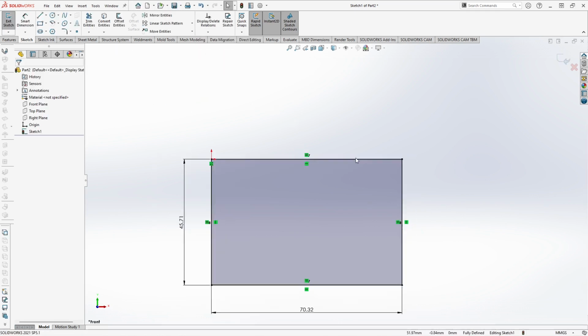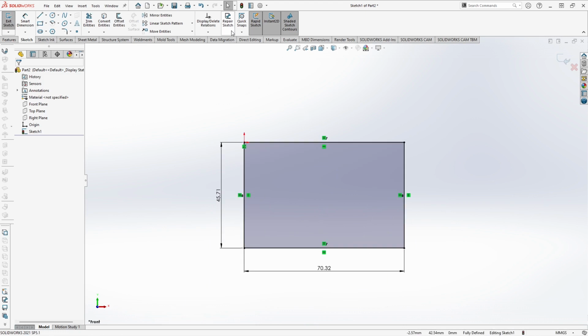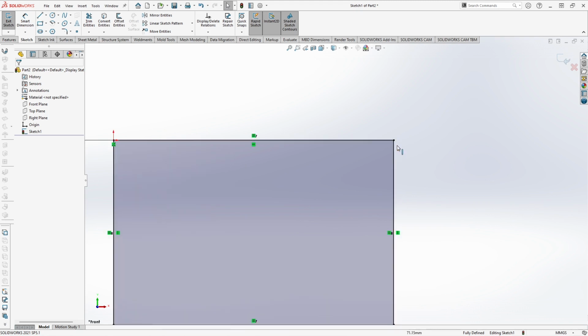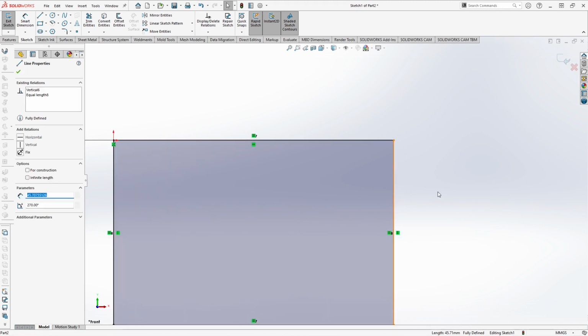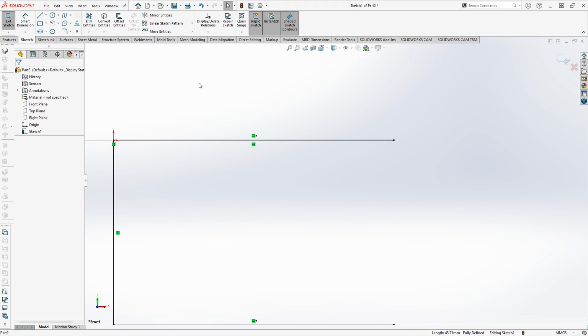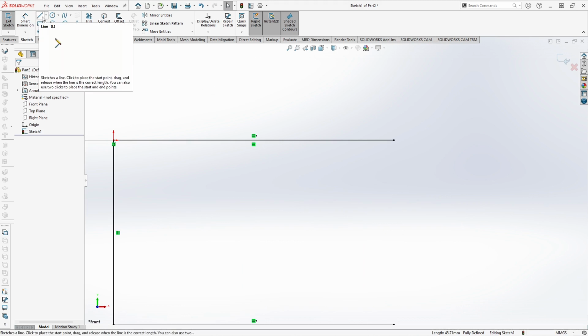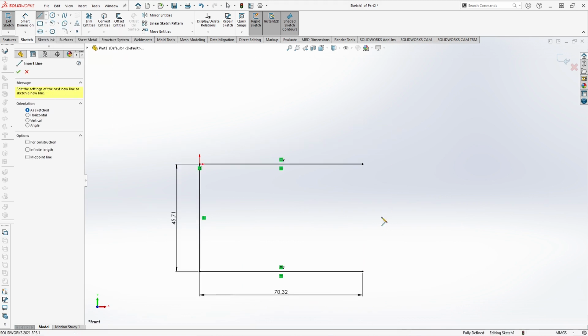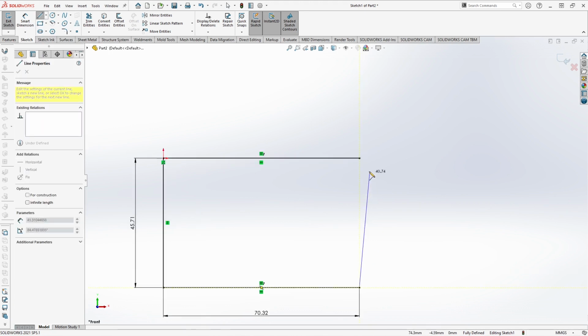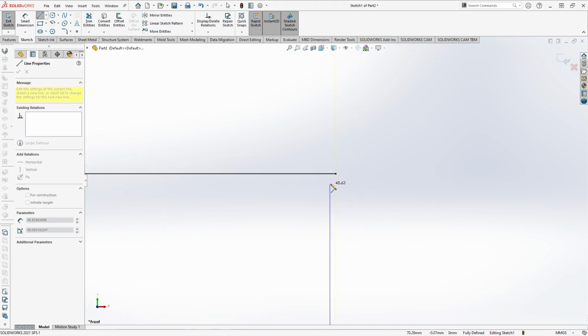So it is defined now. So if I use this command in this, it says no problems found because it is a perfect sketch. It has got a complete loop in it and there's no problem in it. But what if there is a problem? To illustrate that, I'll delete this particular line and I will make a new line, and I will intentionally leave a gap.